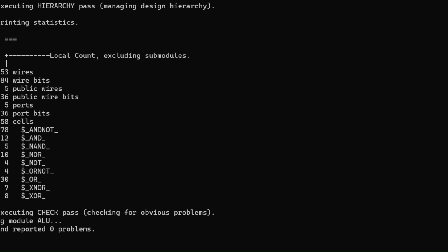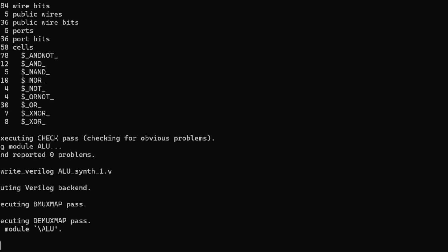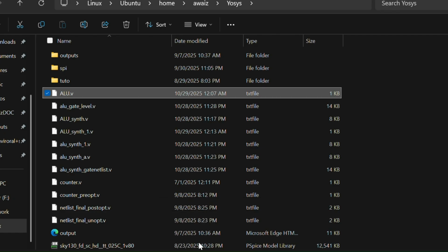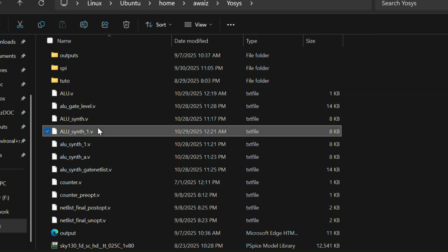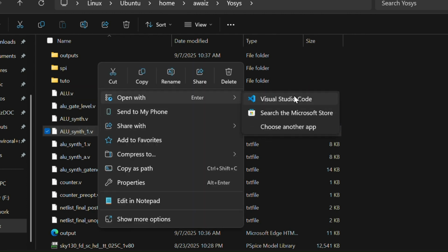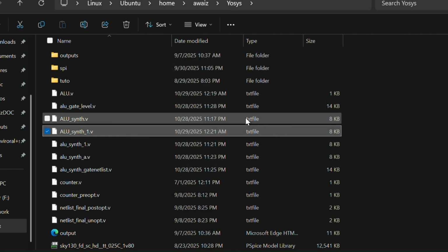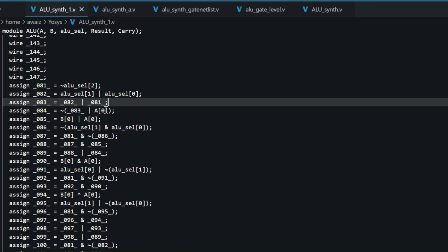Now we will do write underscore ALU. The next step after parsing and elaboration is RTL generation. It converts the behavioral block into an internal form, typically a logic expression. It is not a complete gate level netlist, but it will now have Boolean expressions in it. This stage identifies the combinational and sequential elements and builds a logic equation for each output, like inputs, outputs, and registers. The synthesis file has been set.